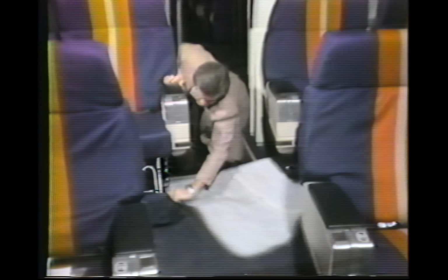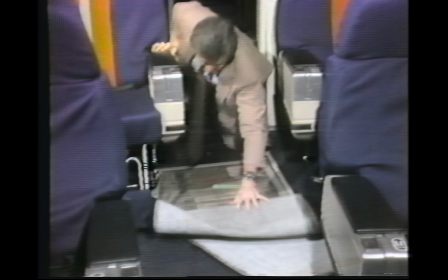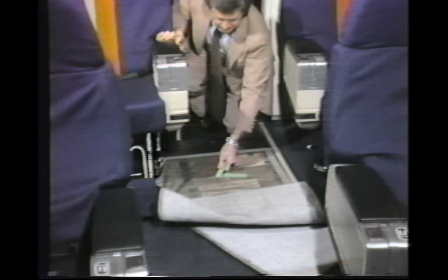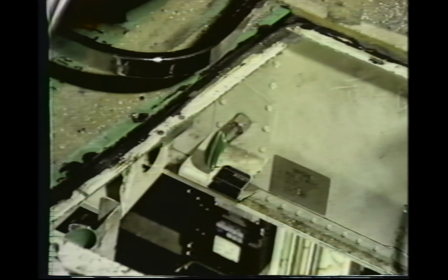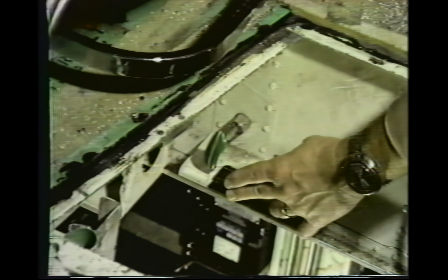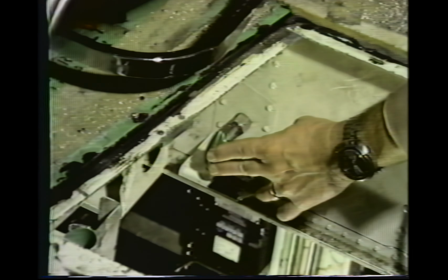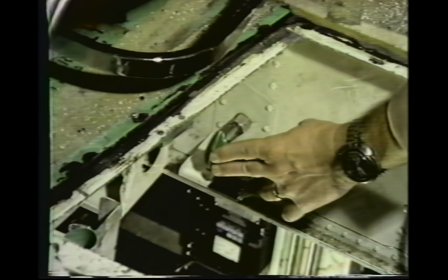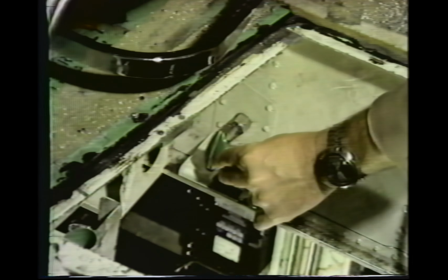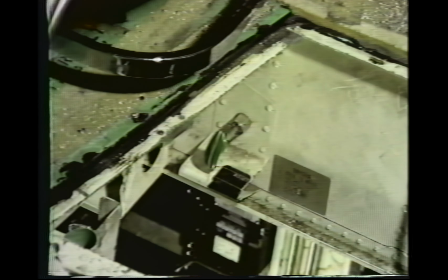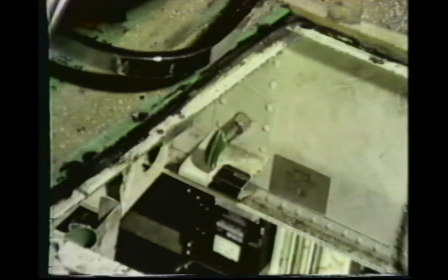The manual oxygen reset handle is located under the access door of the main power center, just forward of the stairway in the main cabin. If an evaluation of the situation indicates no further need for the oxygen system, consider a reset. Pull up the carpet. Lift the access door handle up and aft to remove the door. To reset, push the T-handle aft. Hold for 5 seconds, then return to the normal position.